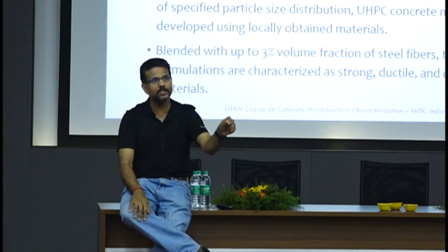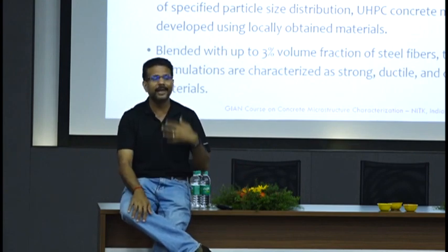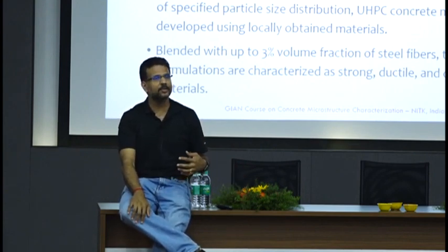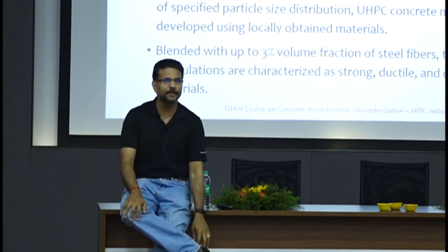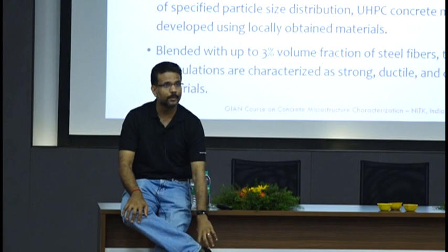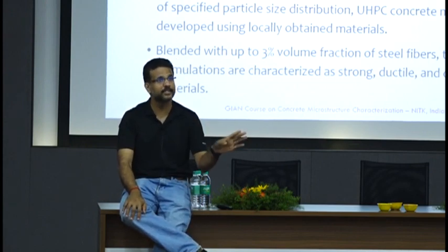So anytime one changes, the other also changes, and there is no one-to-one correlation. So anybody who has told you that fly ash contributes 20% of strength, cement contributes 90%, silica fume contributes 10%, is just plain lying to you. He probably got it in one result. There's absolutely no way that is true for another set of mixes.